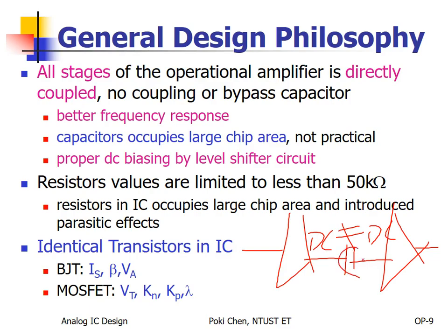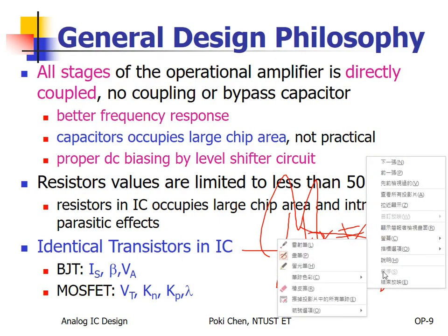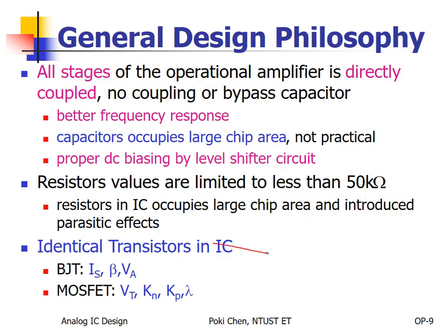Okay, so with such kind of capacitor coupling, we can separate both of them. Only the AC signal can penetrate to the other side. But right now, it is not applicable because we would like DC to be functional. Okay, but again, you need to face the same condition. If the output DC bias doesn't fit the input DC bias of the next stage, what can you do?